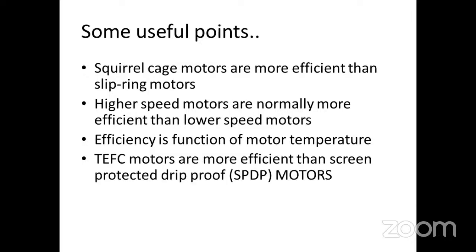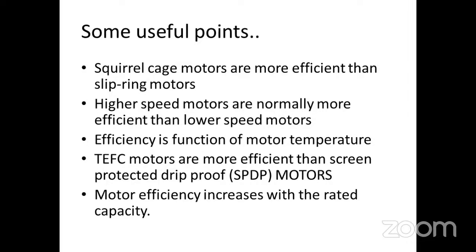TEFC, totally enclosed fan cooled, motors are more efficient than screen protected drip proof motors. Both these types I'll share in the next part of this chapter, sir. We'll just rush up. Totally enclosed motors have less windage losses, that's why they are more efficient. Motor efficiency increases with the rated capacity. These are all universal truths.